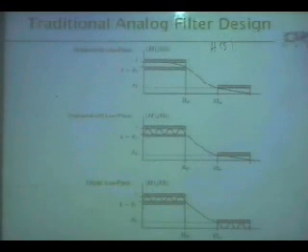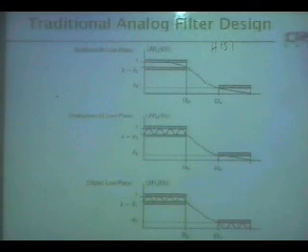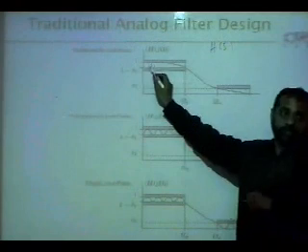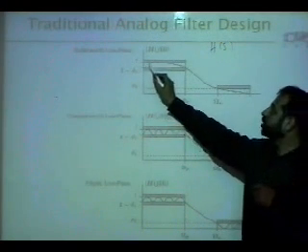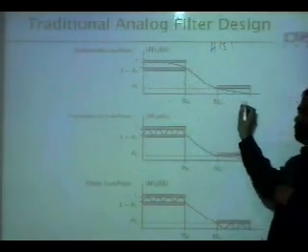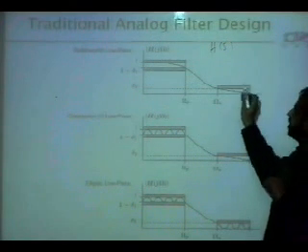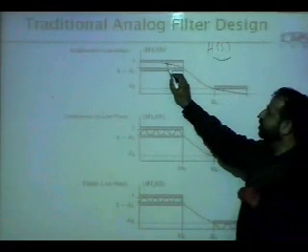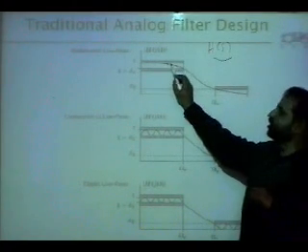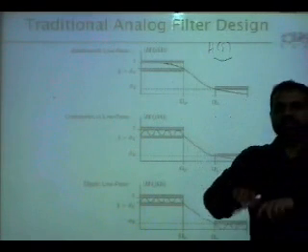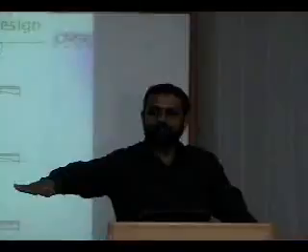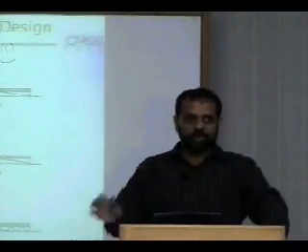So Butterworth. Let's see what a Butterworth is. What are the differences? A Butterworth filter is a filter where people have come up with the idea that the frequency response, again in continuous domain, is a monotonically decreasing function of frequency. A monotonically decreasing function means this point will never be greater than this point, and this point will never be greater than this. So it will have a very smooth frequency response. It will not ripple. It will just go like this. So don't allow it to ripple.